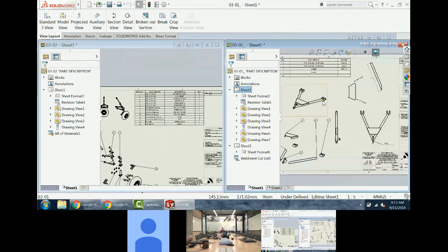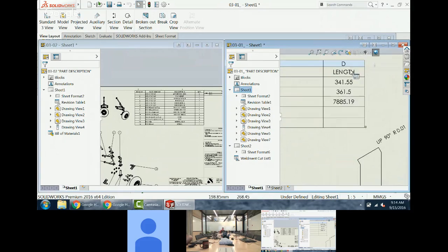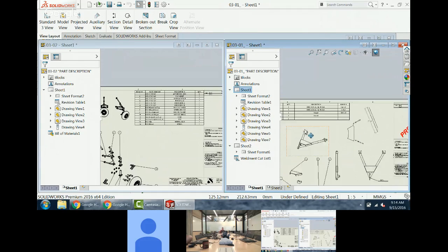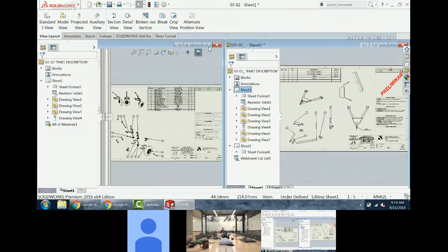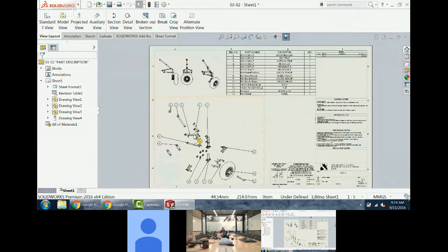Inside the weldment, it's calling out member bodies inside of the weldment. The weldment is actually in a single part file. And the real magic is where it's actually showing us what lengths of tube and whatever types of cross-sectional members you're going to use are inside of that weld. At the assembly level, you can actually roll up stuff that you want. You see, in this assembly, you can actually see that weldment that I was just looking at.